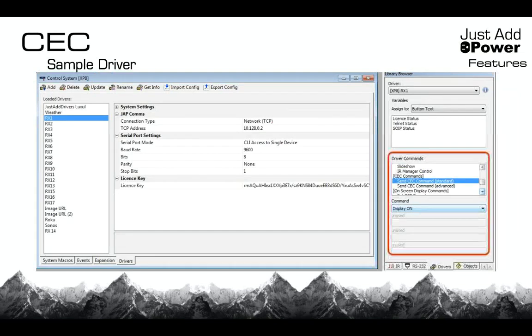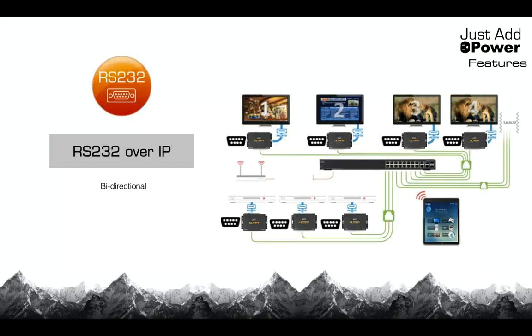Of course, drivers are written for that as well. You'll see that in the drivers. RS-232 is also built into everything that we do. I guess there is additional hardware: you need the DB9 to mini adapter cable. We'll send you those if you need them. But anyway, RS-232 is built into all of our transmitters and all of our receivers, and in all the drivers as well.